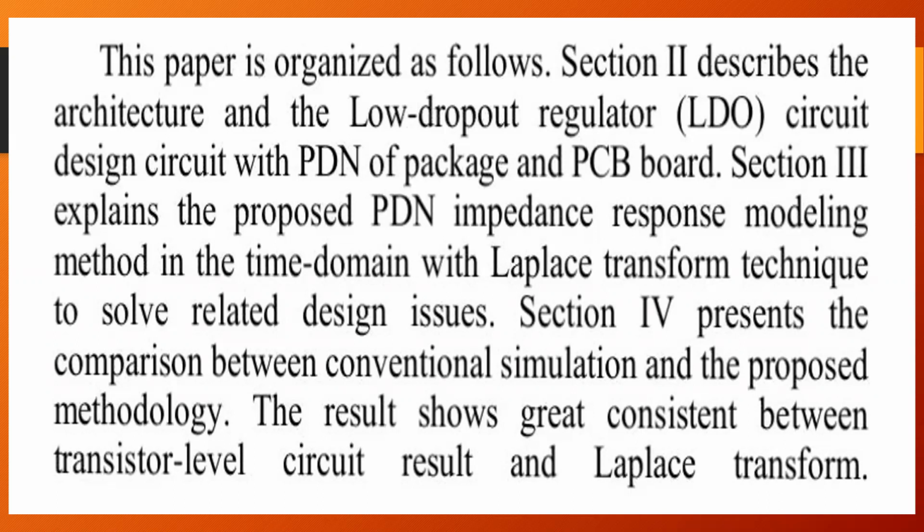Section 2 describes the architecture and the low dropout regulator circuit design with PDN of package and PCB board. Section 3 explains the proposed PDN impedance response modeling method in the time domain with Laplace transform techniques to solve related design issues. Section 4 presents the comparison between conventional simulations and the proposed methodology.